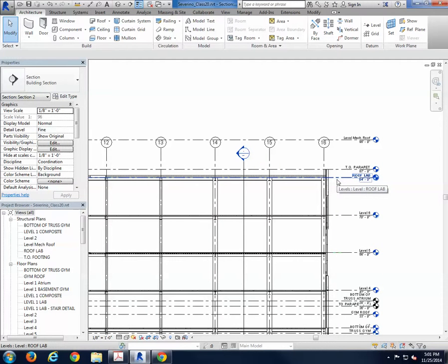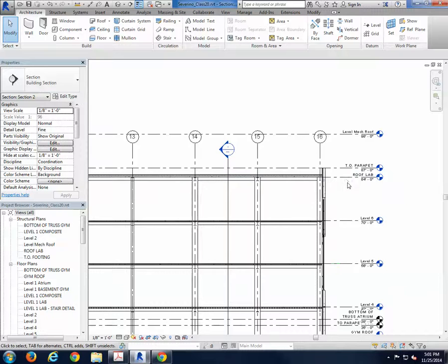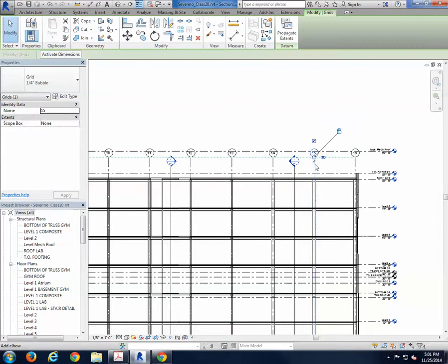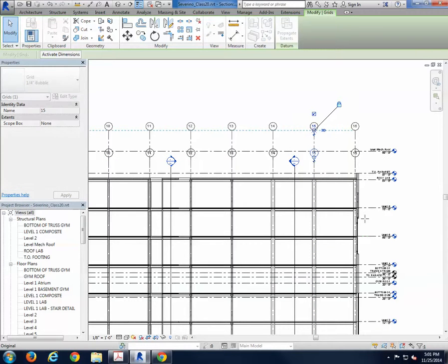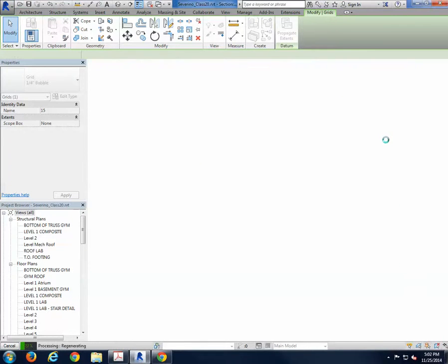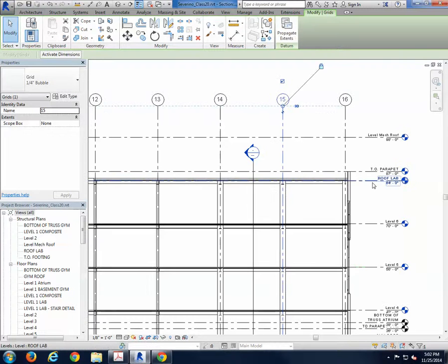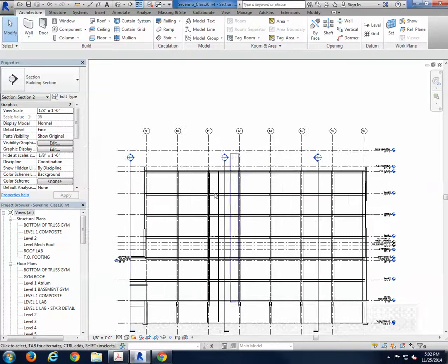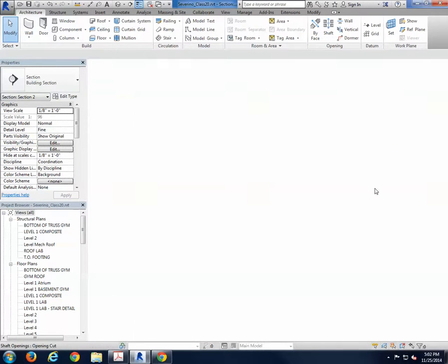That could be actually tricky for some of you because your roof lap is going to be showing the cut, so leave it like that. You don't have to worry about that, but you're going to have to probably change the grid lines to go a little bit higher. And essentially we're going to place walls in the roof level, from the roof level up to the mechanical roof.